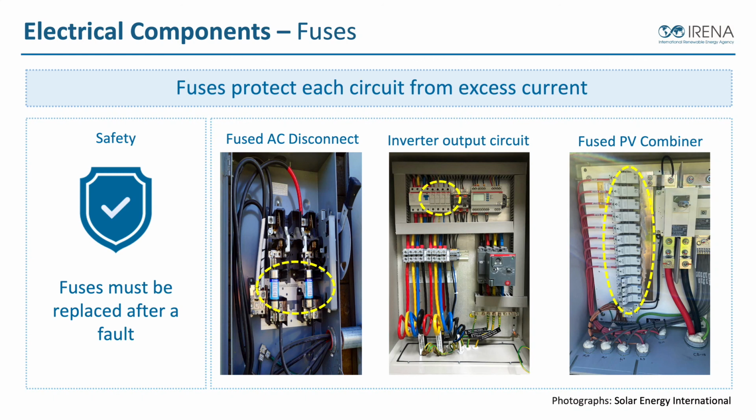Each of those are PV source circuits that are combining together to make one larger solar array connection to an inverter. And we protect each of those circuits with a fuse to make sure that we never do any damage and we have a safe electrical system.